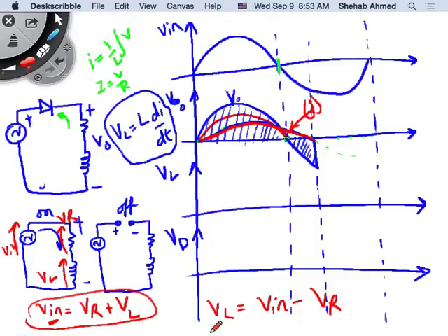You're saying that it can't dissipate into the battery, or your voltage source? No, because as soon as the current tries to flip, the diode blocks. You cannot do that. It will not go back to the supply. You don't have negative current.